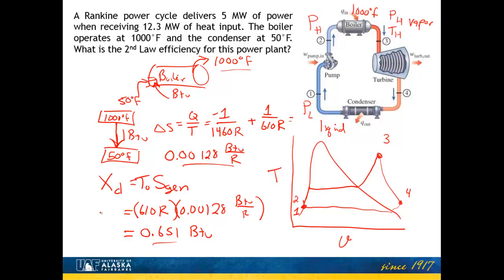Now, if I want to know the total amount of exergy destroyed, we just looked at 1 BTU going into a single pound. I would need to keep computing as imagine this is my material moving through and going along here and along here and along here, and I could sum up all of those, and then I'd need to do it for the rest of the cycle. That would be kind of a long, arduous process, but we can actually solve this a little bit simpler given the numbers that we have.